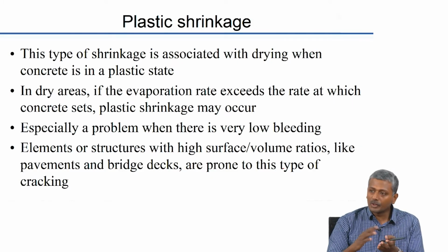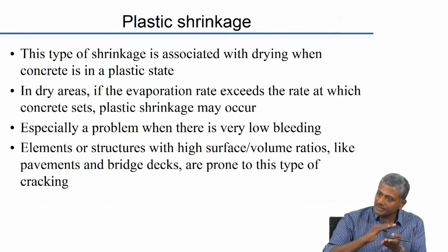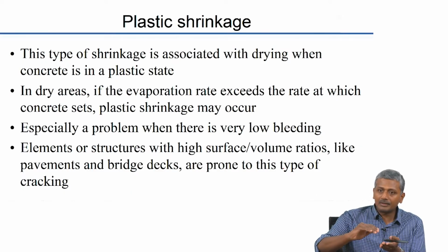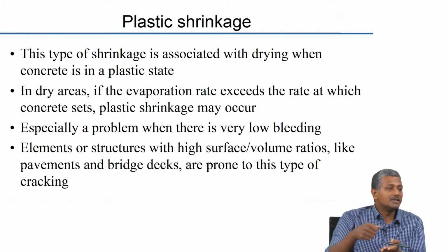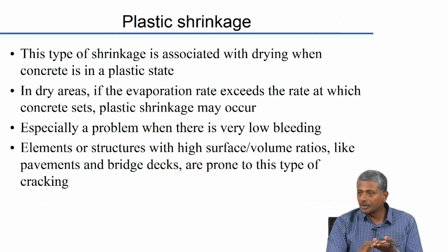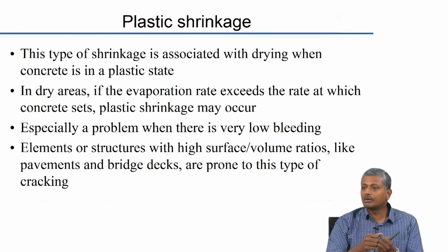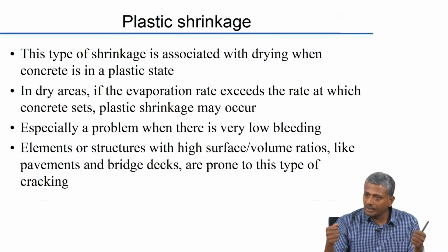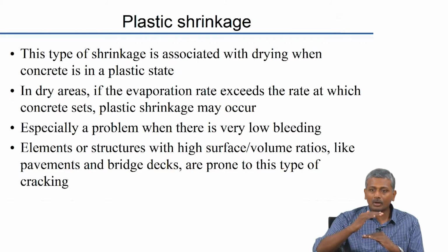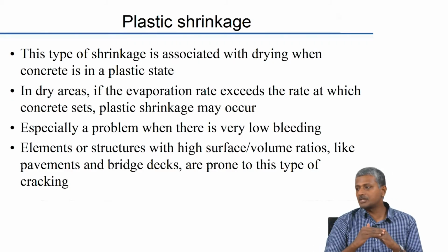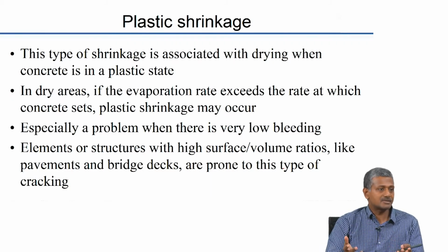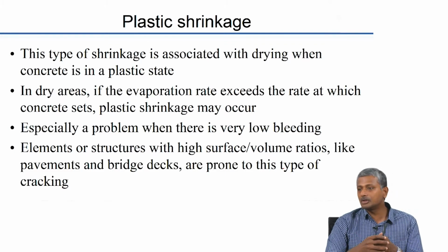But because of that, what really happens is if the concrete is not completely set at that point and the rate of evaporation of the concrete is exceeding the rate at which the bleeding water is rising up to the surface, then the concrete at the surface starts drying, okay. So, since the concrete is drying at the surface, it is volumetrically contracting, but the concrete underneath is not subjected to any drying, and that acts as a restraint which causes cracking in the top concrete, okay.